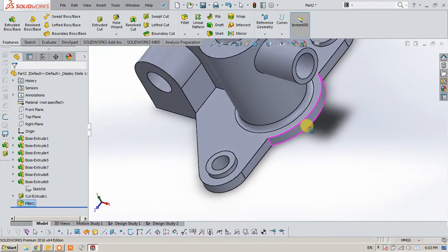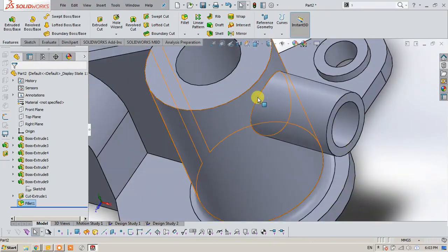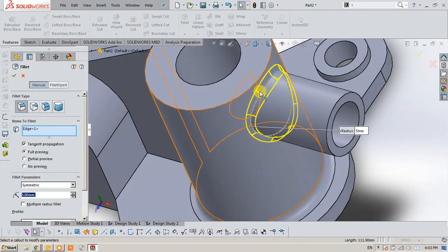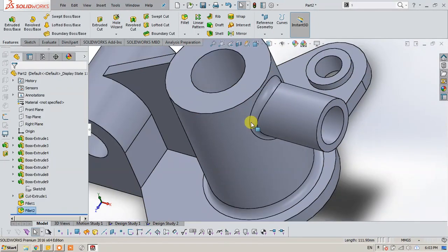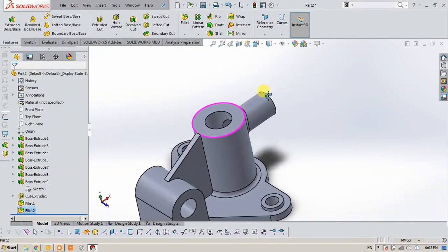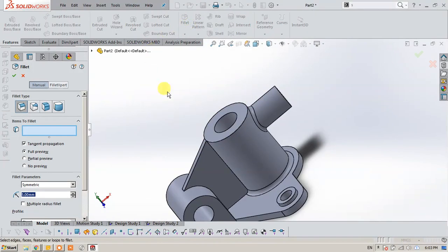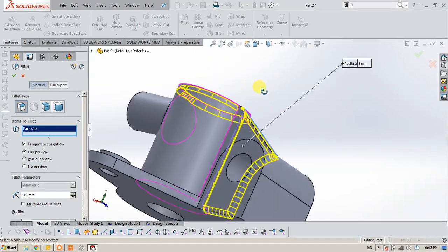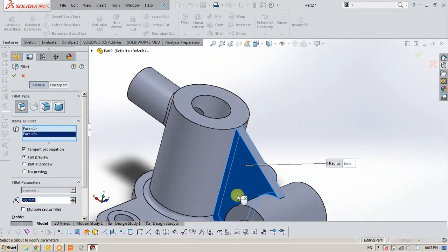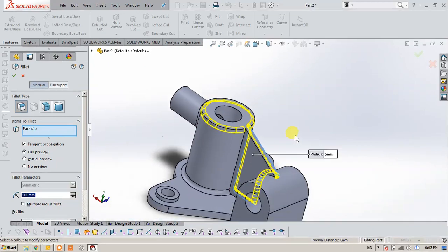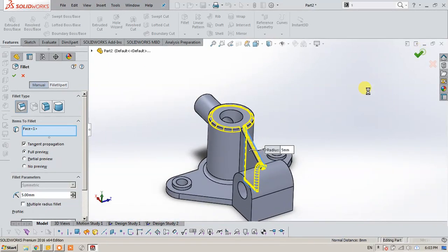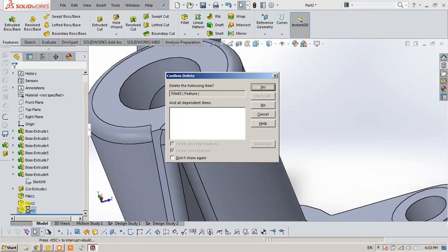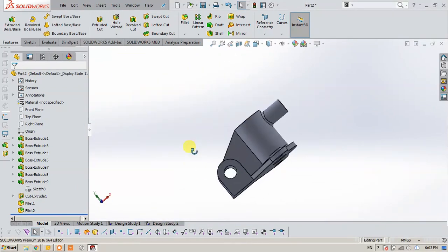We have this fillet, we'll choose this edge and then hit fillet. You'll see it will fillet it around. You can choose a lot of spaces. Also you can do this, just fillet, choose a face, and then it will automatically detect the edges around it. Choose this face also. Another trick as well. As you can see, it fillets all around. I just don't need that fillet. Okay, you can play around with stuff.